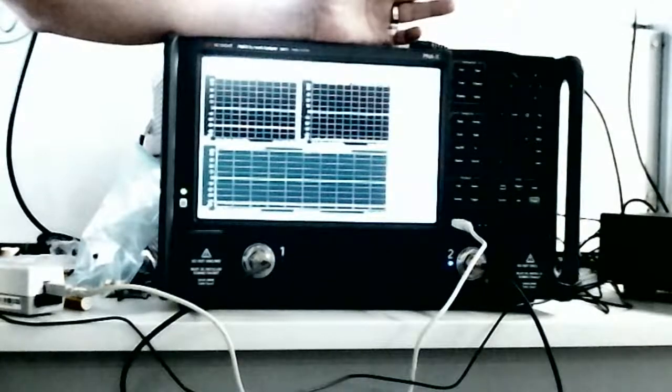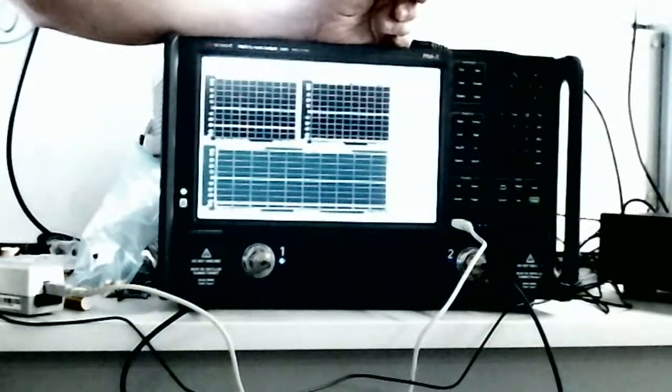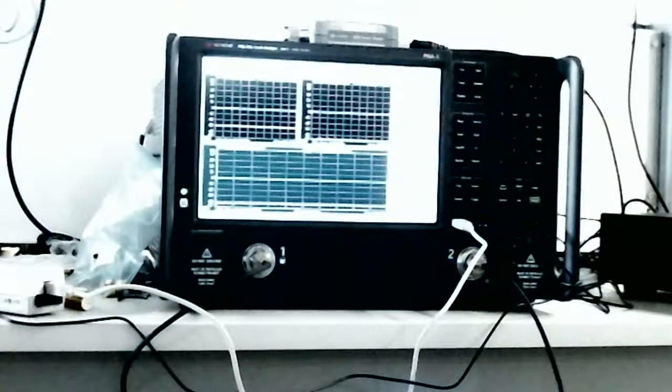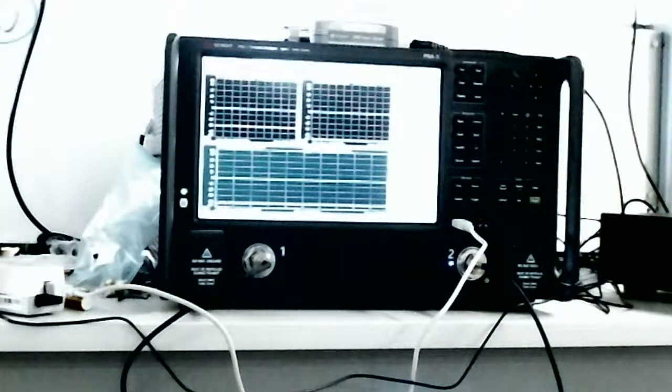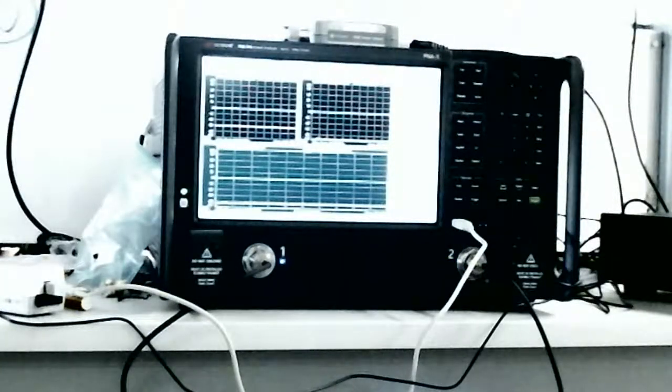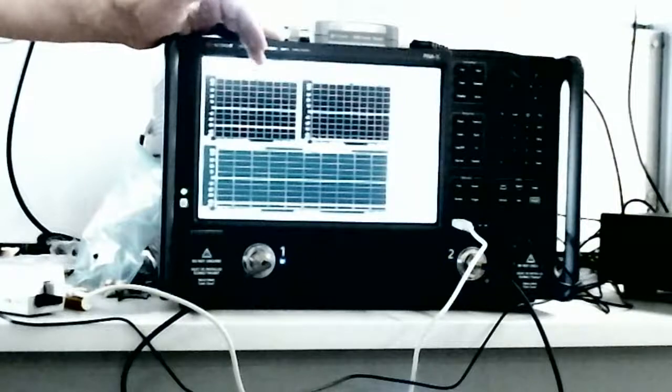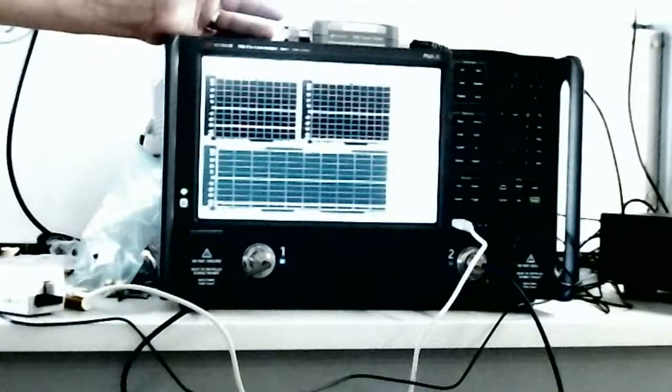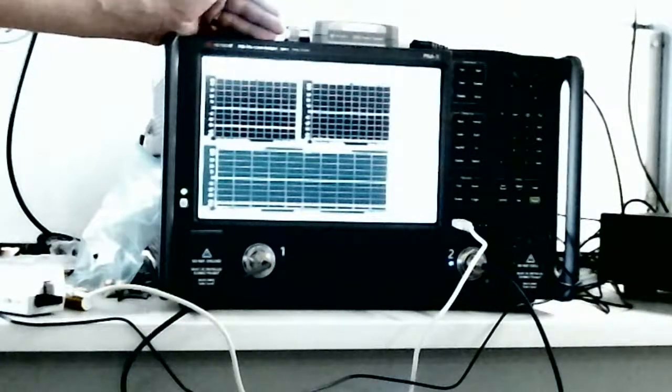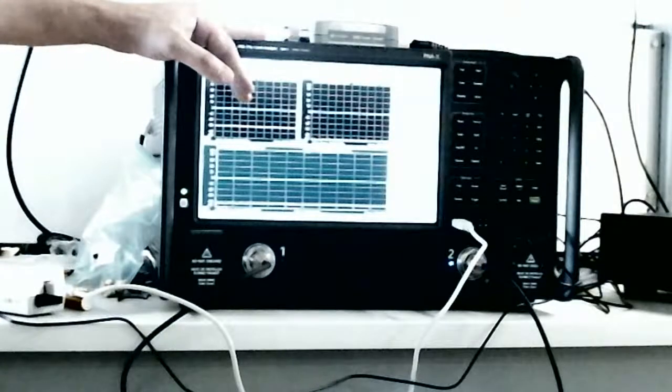So in terms of impedance, this is 50 ohms, right? Correct. So if we have other measurements like 75 ohms or something, can we do it? So you can. What I would recommend there is a 50 to 75 ohm balun that you can buy from Keysight, or you can get it from somebody else. You can put it on here, and then you can change your system impedance here. So